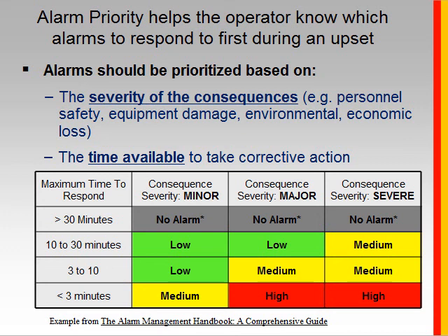There's no way an operator can respond effectively or have a likelihood to respond in time and correctly within 3 minutes. So they would say you need to redesign the system so that the operator is not put in that kind of a position where he has less than 3 minutes to respond to something that could end up with catastrophic consequences. So this is just a recommendation and a starting point, and it needs to be adopted for each individual plant situation.